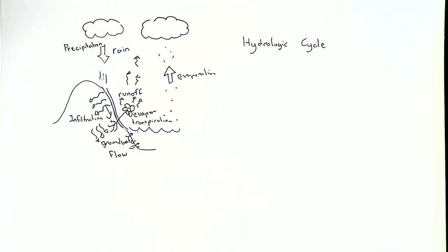We control these water resources in terms of where they are, how much is released, how much is produced or brought in, and even how they travel. Sometimes we do this process called routing, which means you have this much water, it's too much for my parking lot drainage to handle, so I make a really, really long system so the water spends a lot of time traveling, so that by the time it gets to the end of the system, it would have been a smaller or lower rate. Good. So we control it, essentially.